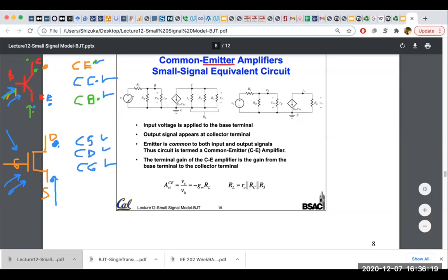And all of them have different characteristics. What does different characteristics mean? Well, we define three important things: R in, R out, and gain of that one-stage amplifier, AV. So, for instance, common emitters will have a high gain, and let's say it will have a low R in and high R out.